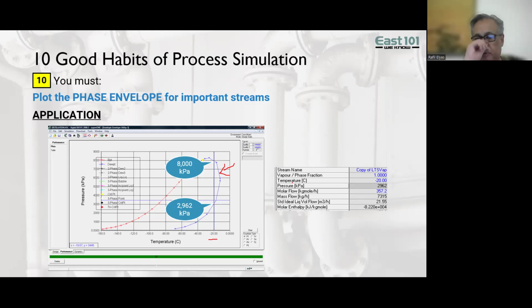Yeah. So if you remember from the thermo class, if you've got components whose boiling points range from really, really light, like methane, about minus 162 degrees Celsius, all the way up to really heavy components with boiling points of over 200, 300 Celsius, you can get phase behavior that looks like this. Yeah, this retrograde region. What it means is some of the molecules are at their critical states where some other molecules aren't. That's why you have a bulge.